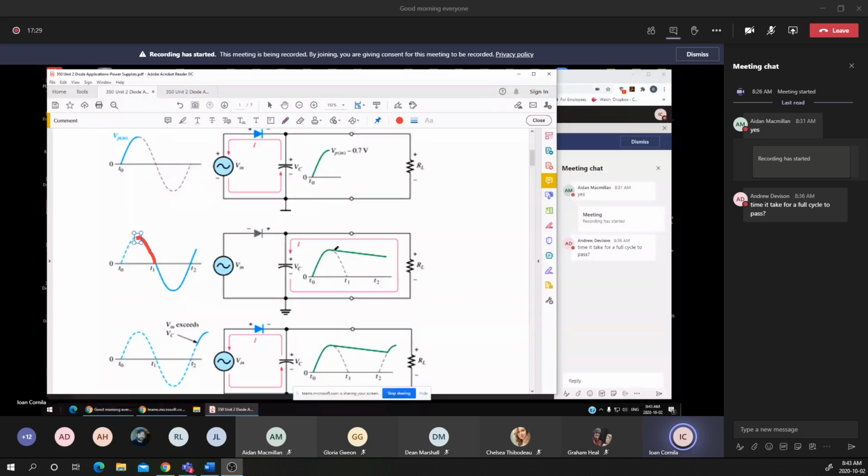You notice that from the peak voltage, the input voltage is decreasing to 0. The negative voltage is suppressed due to the half-wave rectifier, due to the diode. This means that for this period there is no voltage supplied to the capacitor.